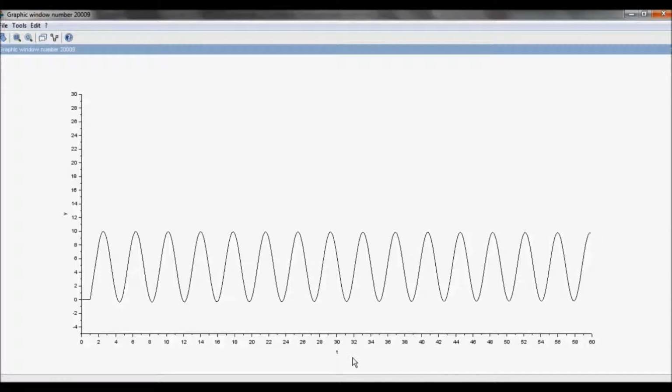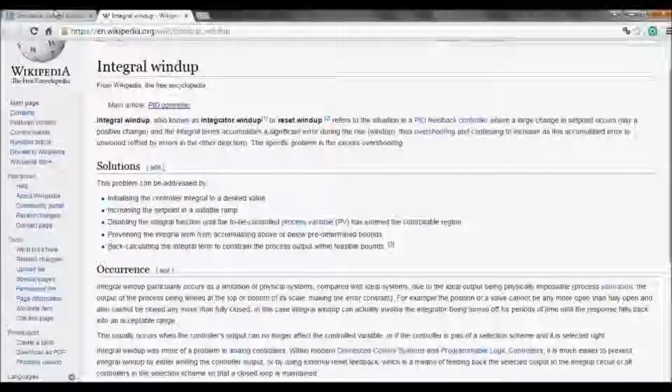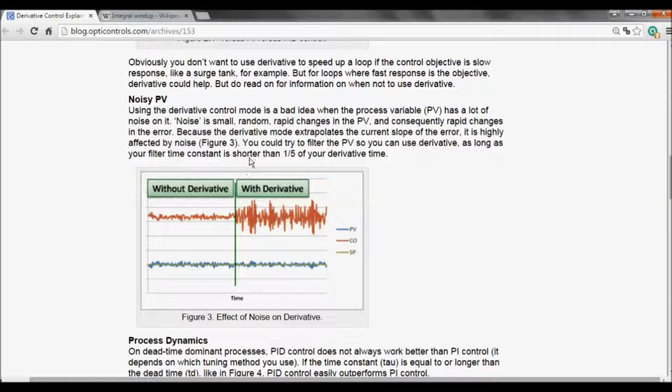The controller code is programmed in the Arduino interface using the proportional and proportional-integral strategy with anti-windup. As the sensor returns very variable measurements, the integral of the error will go to infinity, making the control impossible. The derivative control was not applied because of the high variability of the ultrasonic sensor, which would cause the derivative kick, and because this measurement variation is caused by the sensor itself, not by actual variations in the vessel level.